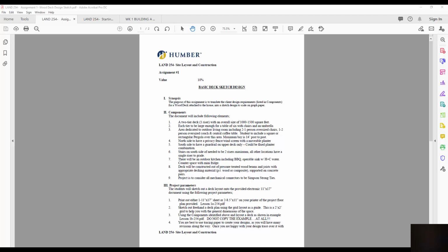Once we reach 3 risers, it changes how the Ontario Building Code has this requirement set out for staircases. So we're going to limit it to 2 risers, or basically 2 steps. And all other locations will have a single riser or a step down from the deck to grade level. And again, that's to meet certain code requirements.